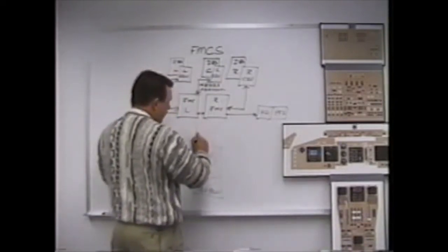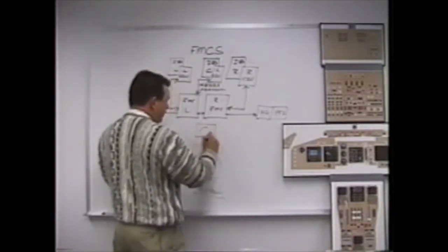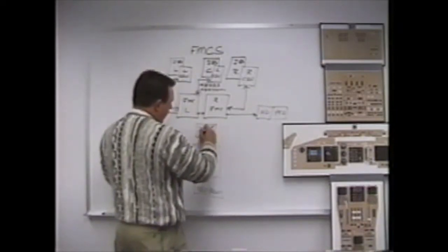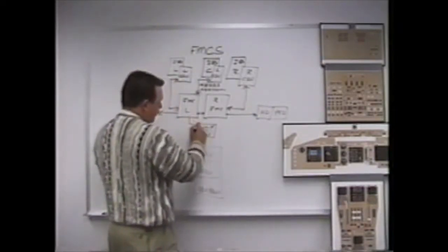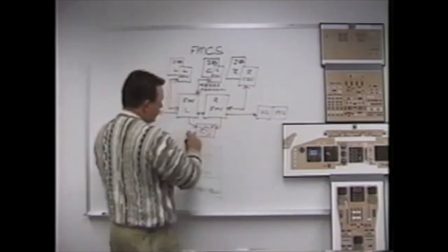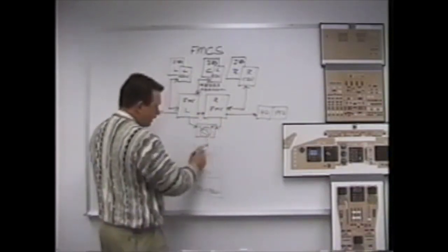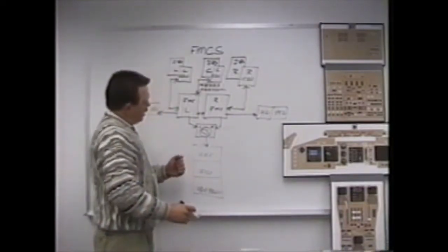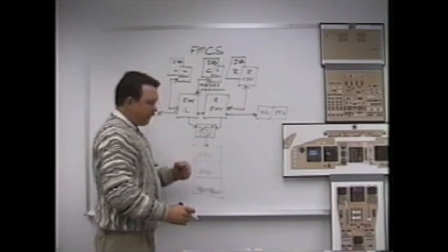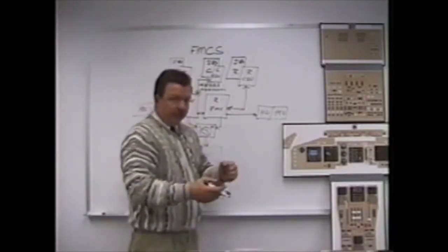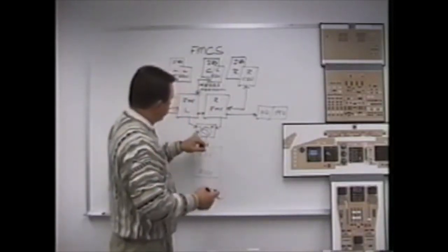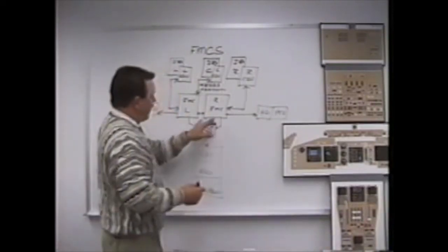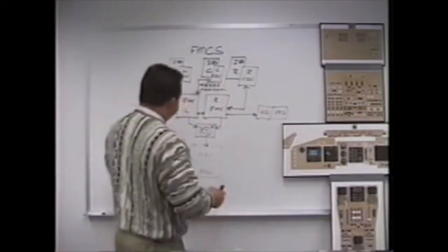Which FMC will control my airplane systems? That's through the FMC master selector on the center panel. Everything being normal, we typically, per SOP, select the left FMC, which gets to talk to my EECs, my flight control computers, and my nav radios. The reason for the left FMC and not alternating between left and right like we do on every other thing is because the left FMC has the backup power source. The right FMC does not have a backup power source.